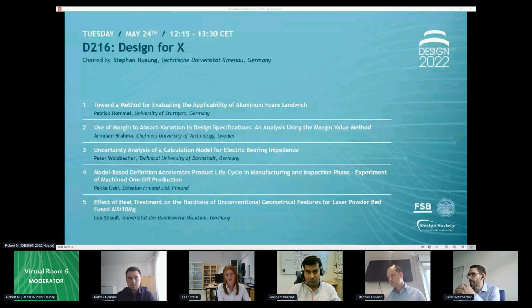Of course, if you start at this point, you have to consider a multitude of different points, like if it's caused by a disturbance factor, you have to consider the origin of the disturbance factor. You can just shield your sensing machine element or sensory function, or maybe you can add different sensors to measure the disturbance factor and then get rid of it in the post-processing.